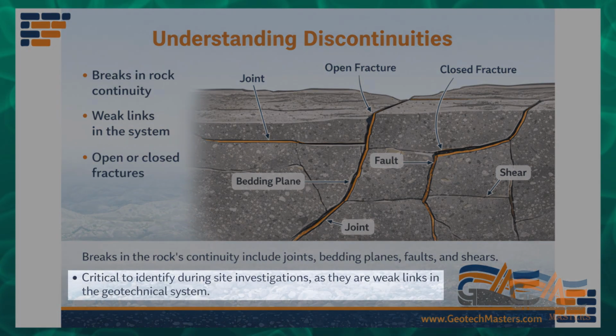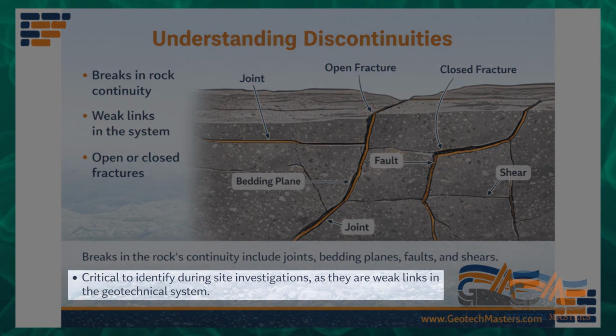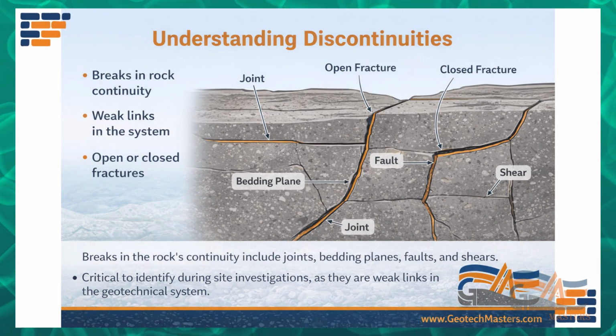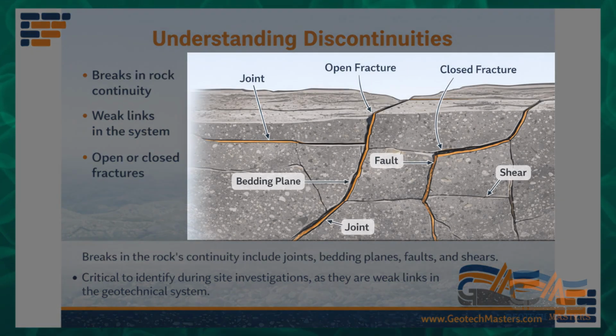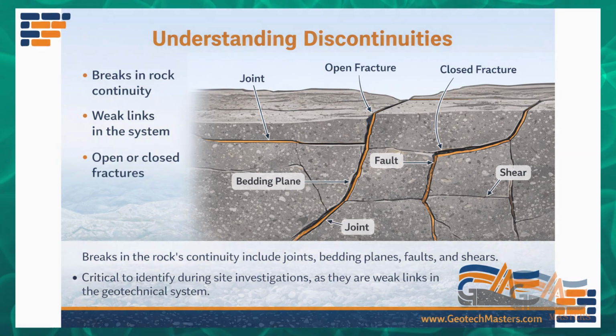When we perform site investigations, identifying these breaks is critical. If we only test the solid core, we miss the most critical part of the ground's behavior. We must measure their spacing, orientation, and condition. We will cover how to measure these in detail in later episodes.